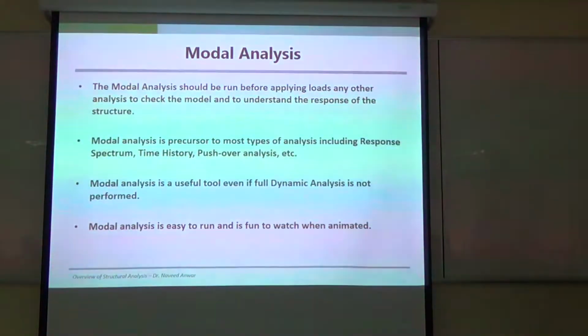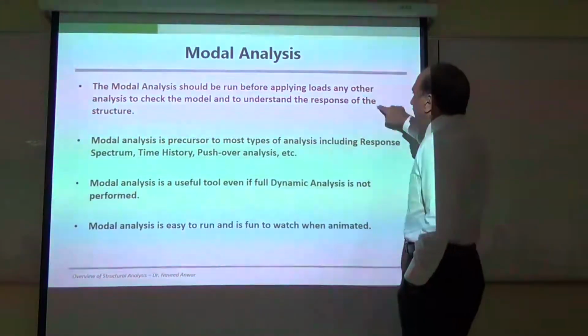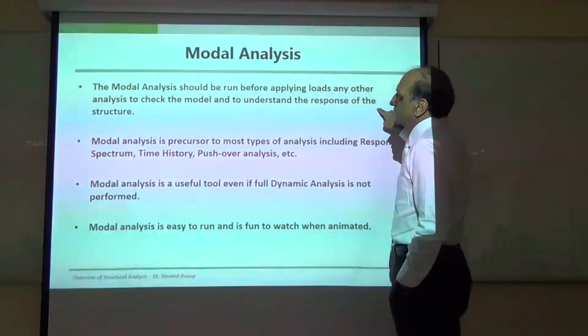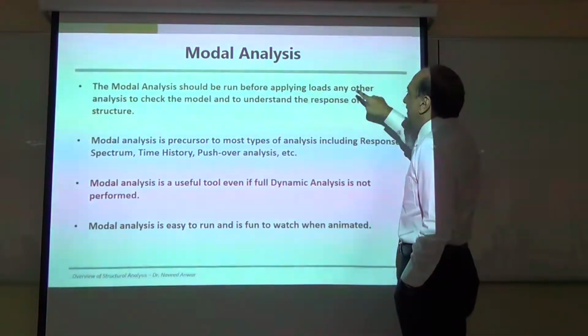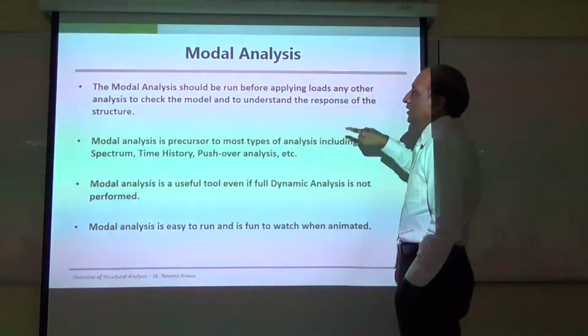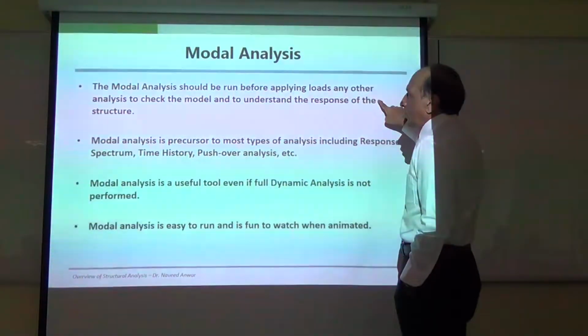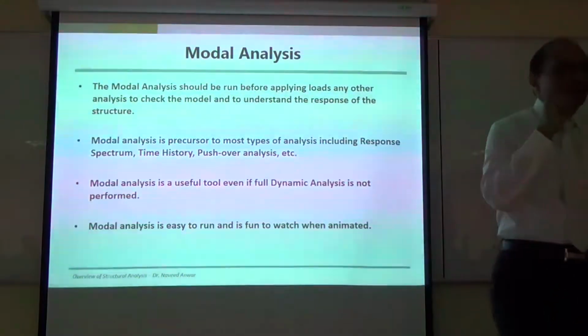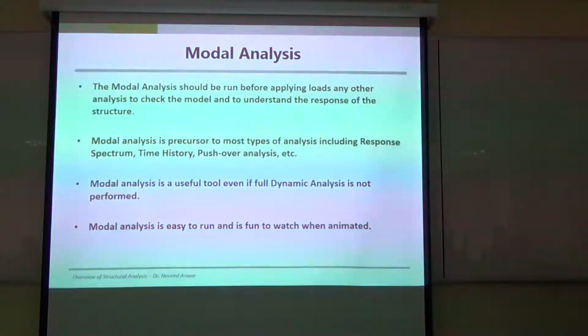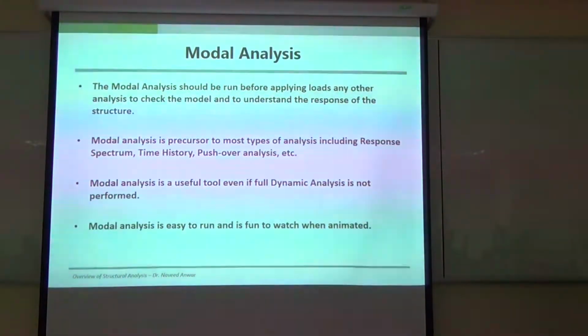And this is very important. Point number one. Modal analysis should be run before applying any loads or any other analysis to check the model and to understand the response of the structure. Do not forget this. When you do any analysis, even for dead load, you must run modal analysis first, because it can tell you whether your model is correct or not. It can tell you whether your density is correct or not.